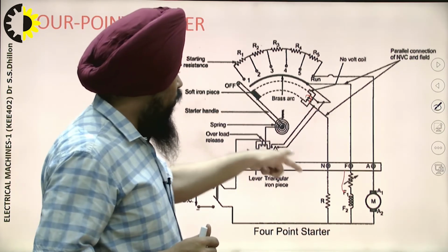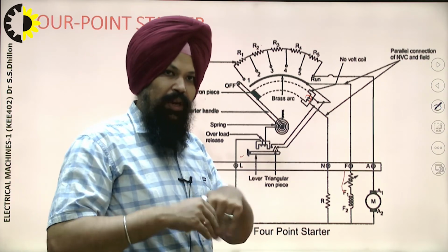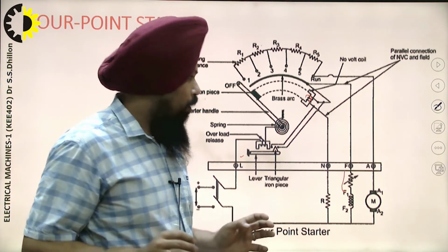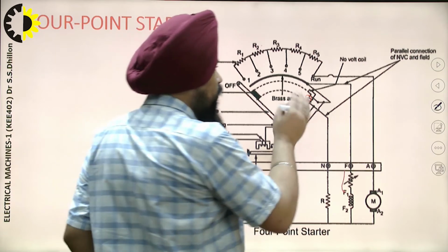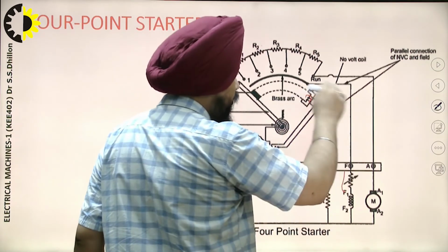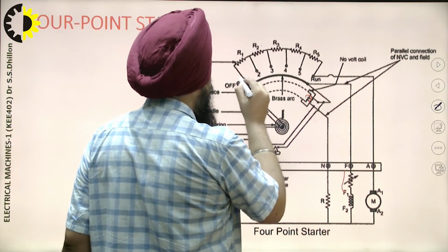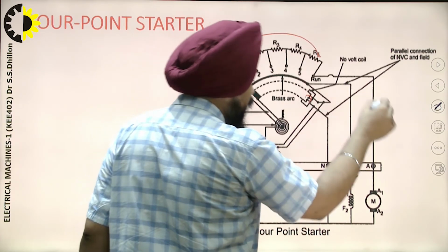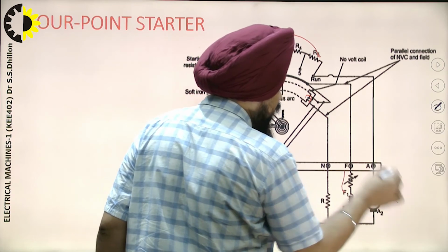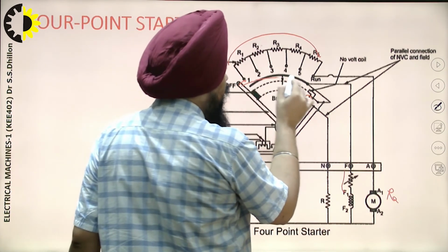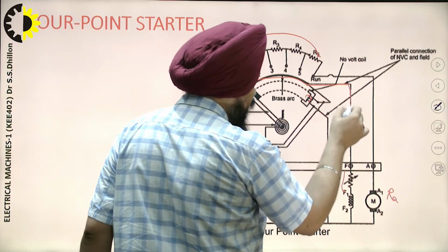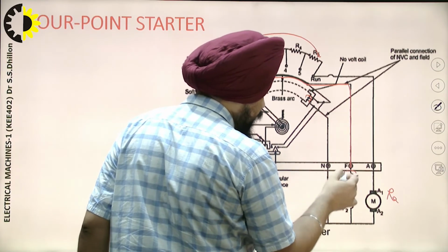In order to eliminate that kind of problem, what we have done is separate out the field resistance, the field circuit. You can see over here, as we go to stud 1, this whole resistance is added to the armature resistance as we discussed previously, and this field circuit has the full voltage along with the rheostat.